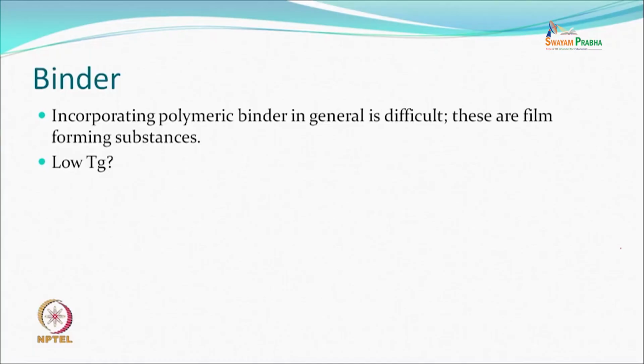challenges. The polymer should have low glass transition temperature. Whenever you make any film or laminate anything on top of the surface of the fabric, rigidity increases, flexibility changes, and you don't want that. So how do you help that? Low glass transition temperature, that's what helps the cause.